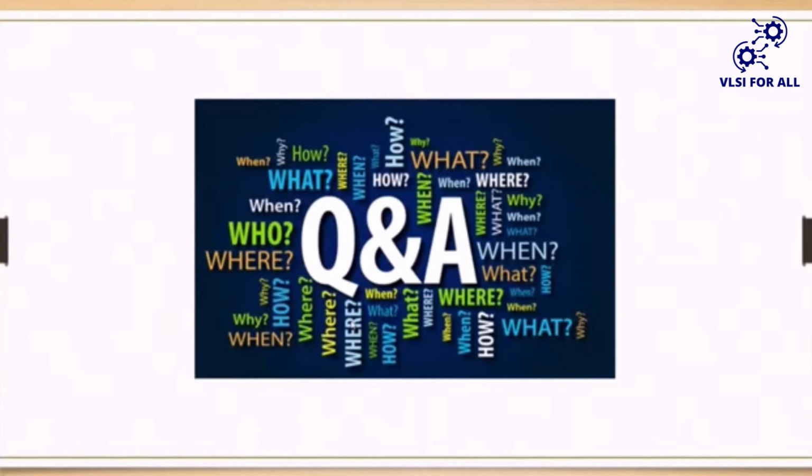So there are three sanity checks based on your stage: check design, check timing, check library. Of course, during logic synthesis you don't require .lef files, so no need to perform check library. However, if it is PNR, you require .lef files, hence you can perform check library. So there are three checks: check design, check timing, check library.